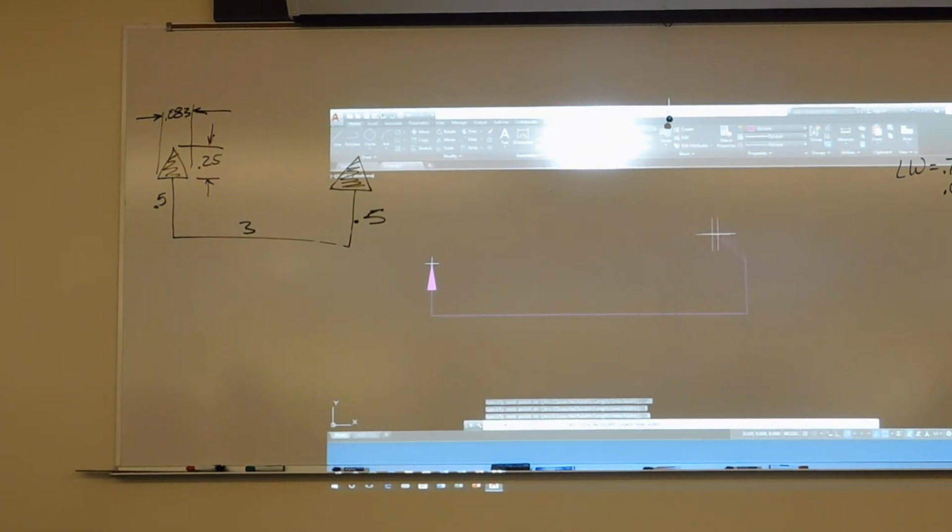I think I had a typo on my arrowhead. All right, so then we get ready to make our next arrowhead. Okay, now this time you're going backwards, right? You're starting with the fat part of the arrowhead and going to the tip. So again, go to width, W, enter. Start with 0.0833, end with 0, and make the length 1/4 inch. And you should end up with this line. You can terminate it once you finish your arrowhead.